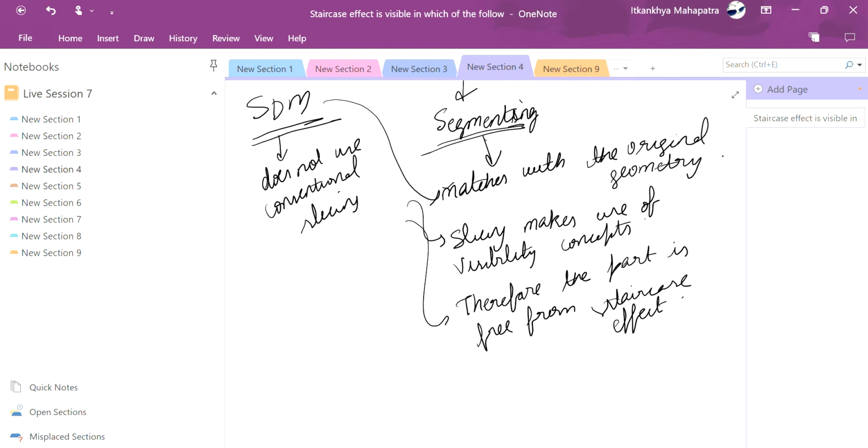But suppose, as you're talking about the FDM process, I'll give you a simple scenario. Let's take FlashPrint software, which is a software for the Flashforge company. Here you take an STL file from SolidWorks, you have taken the CAD model, and you import it in the FlashPrint software. In that software you give all other parameters, and when you save it, you don't need to provide any codes. You save it directly in .gx format.